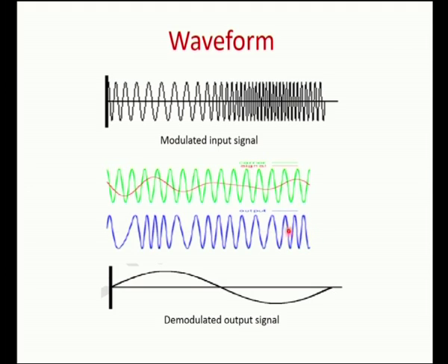This signal will be given as input to pin number 2 of the 565 PLL. So, by tracking the changes in the frequency, we get a demodulated output, which is nothing but this red color waveform itself. Similarly, if you are going to provide an input of FM modulated signal whose message signal is like this, we get a demodulated output as the same.